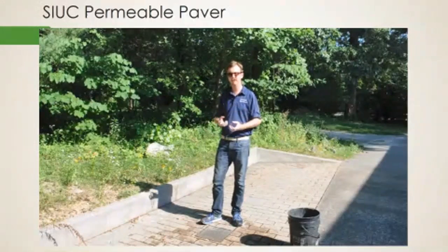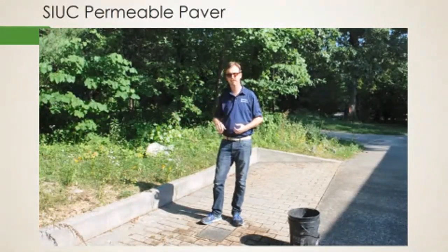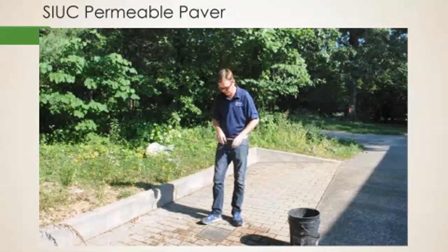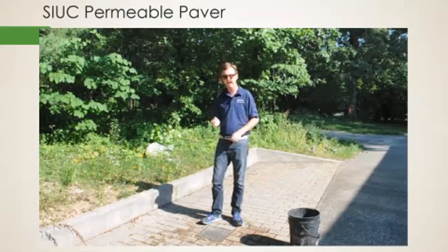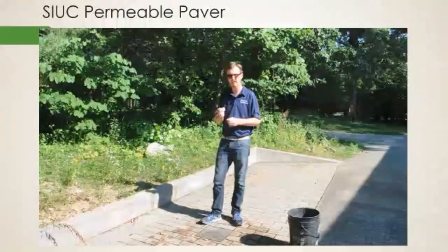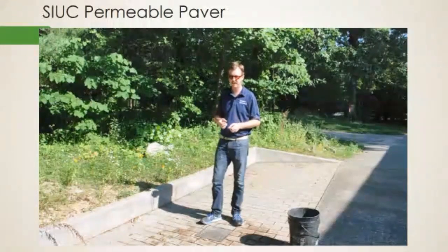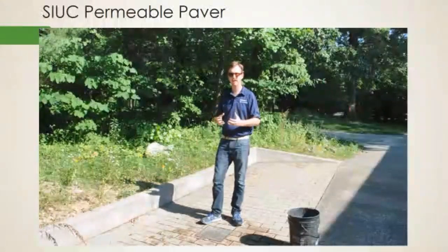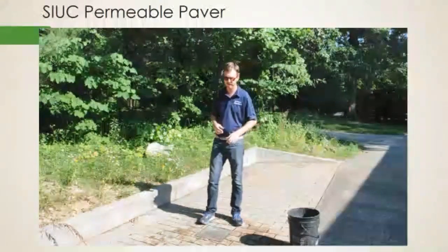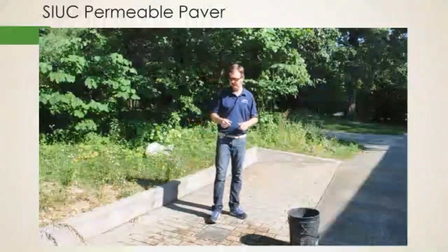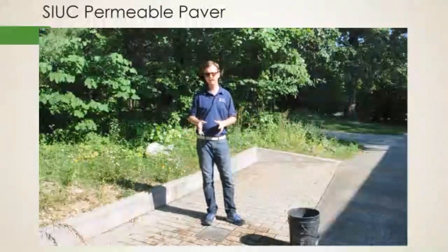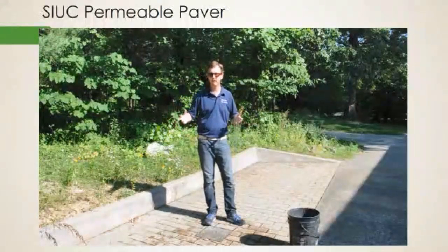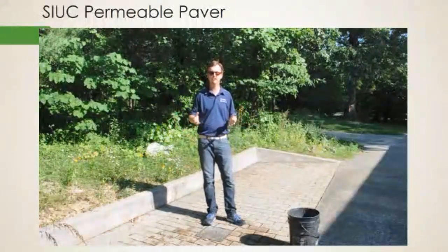So that's really helping to wick away water quickly, give it a place that it can more naturally absorb back into the soil. And in between here there's a light grade aggregate, a very small grade aggregate, larger than sand. We don't want something in between there that's going to be able to compact and over time turn into more of an impervious situation. So that's how this system works, and this is a pretty common system for walkways and public spaces, where we have foot traffic.